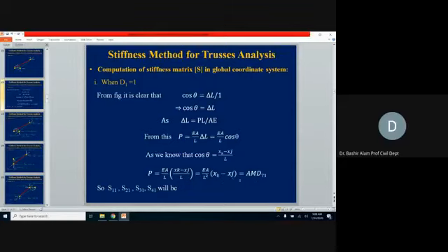And actually, this member force is our AMD in member 7 because of the displacement in one direction. This is how we write the description of this AMD, member end force. Meanwhile, we are generating our AMD matrix also, and its notation will be AMD 71. 7 is coming from the member number and 1 is coming from the region where we are giving the displacement.